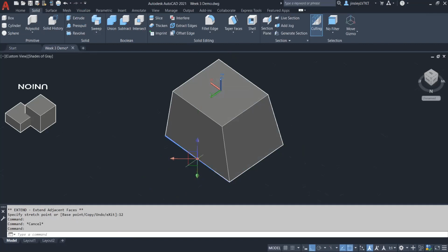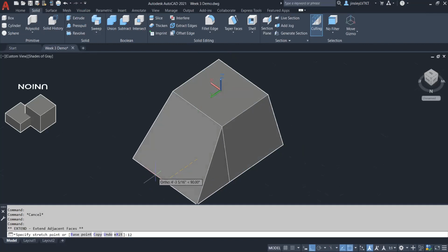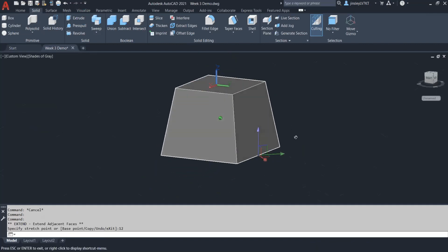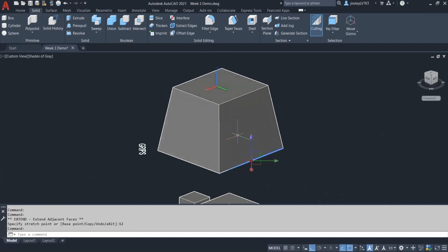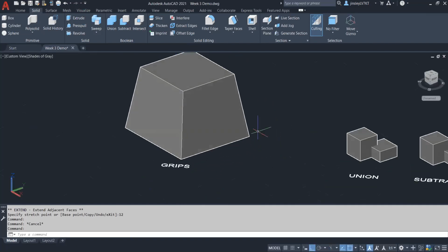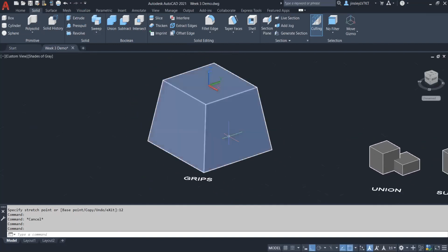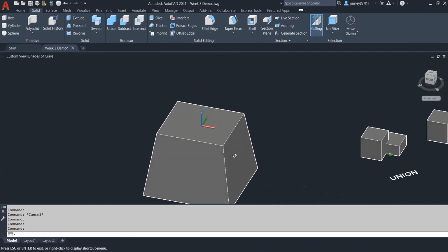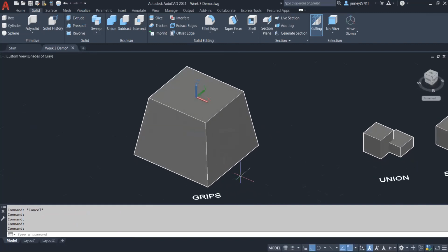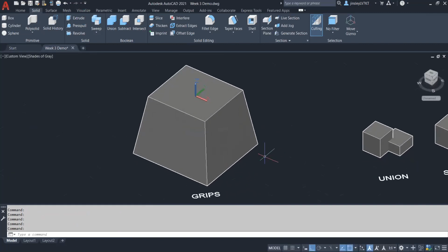And I could actually create a shape that has a little bit of a transition from the bottom to the top, right? Which is really common in concrete for foundations and columns and whatnot, to give it strength, okay? But being able to move these objects, you want to make sure that you have your X, Y, and Z aligned to that face properly, right?